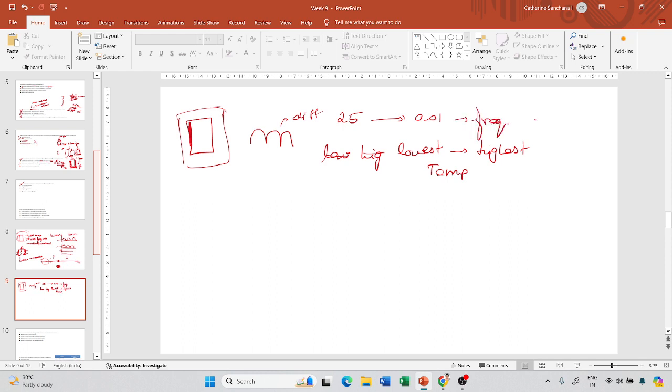Why is it like that? Why do you think you should go from highest frequency to lowest frequency, or lowest temperature to highest temperature? If you see, at higher frequency the material will behave solid like, so it will not have residual strains. Also at the lowest temperature, your material will behave solid like, and so it will not have irrecoverable strains, as much as a lower frequency or a higher temperature has.